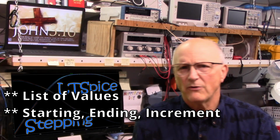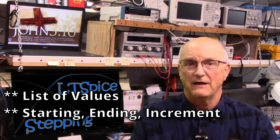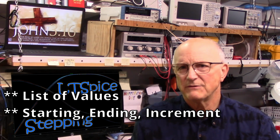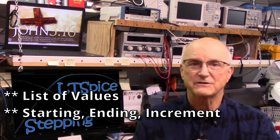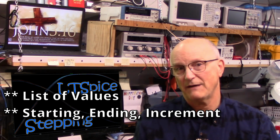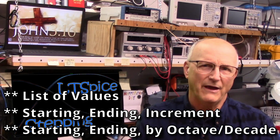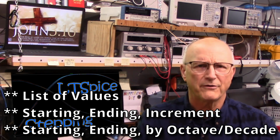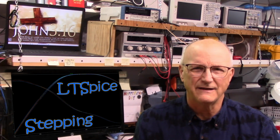For example, you might want to start with a value of 1 microfarad and end with a value of 2 microfarads. If you step through using an increment of 0.1 microfarads, then it will simulate the circuit using 1 microfarad, 1.1 microfarads, 1.2 microfarads, and so on, all the way up to 2 microfarads, if you choose the linear method of stepping. On the other hand, you could do a similar thing using an octave or decade method. Now, with this one, you have to choose the number of points per octave or per decade. So you ask, well, what is meant by an octave and a decade?